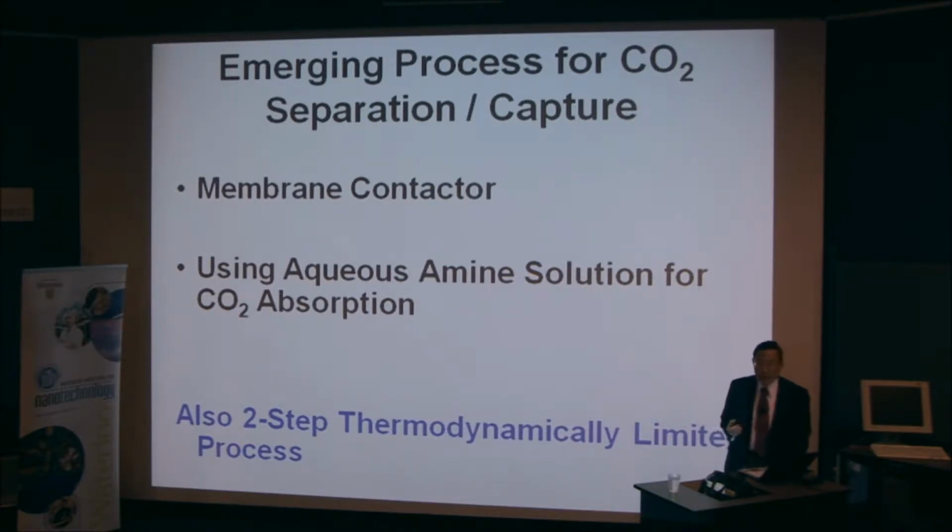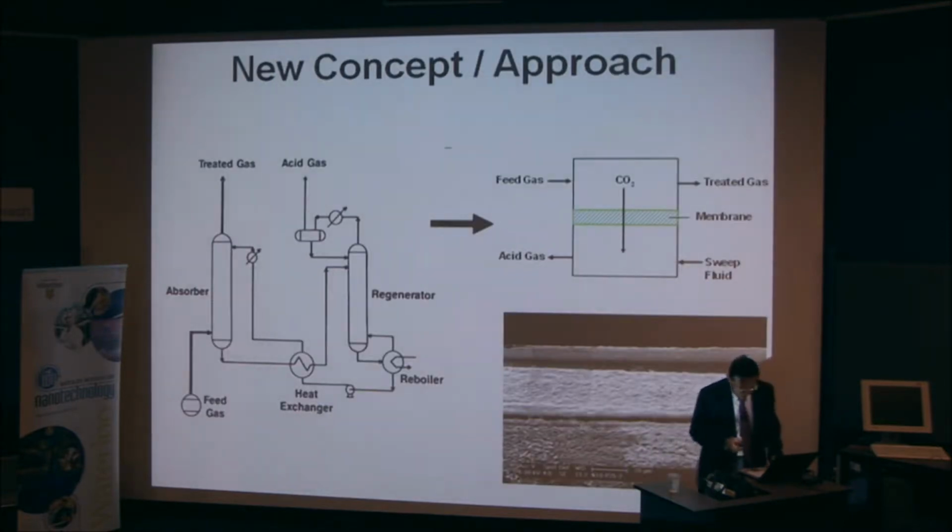There are some emerging technologies, including the use of a membrane contactor that provides a very high mass transfer surface area per unit volume. They also use aqueous amine solution for the separation. And again, it's still a two-step thermodynamically controlled process.